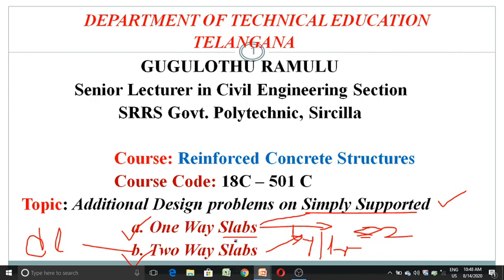Whereas in the case of two-way slabs, we calculate the maximum bending moment in two directions, the x direction and y direction. There are some codal provisions for that. Based on the codal provisions, we can calculate Mx, the maximum bending moment in the x direction, and My, the maximum bending moment in the y direction. These Mx and My values depend upon bending moment coefficients, which are given in Tables 26 and 27 of IS 456-2000. Based on the type of slab, we choose the bending moment coefficients alpha x and alpha y, where alpha x is the bending moment coefficient along the x direction, and alpha y is along the y direction.